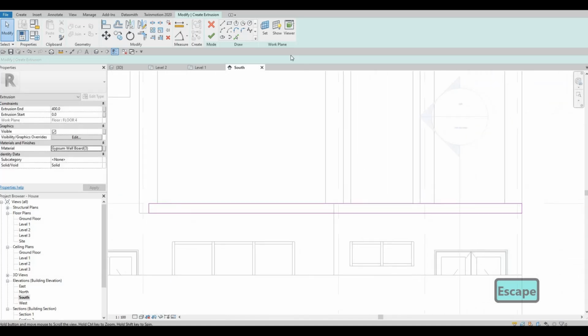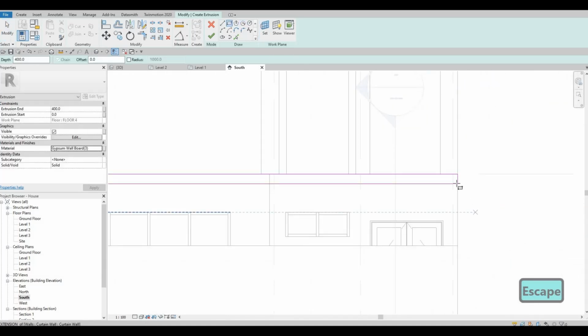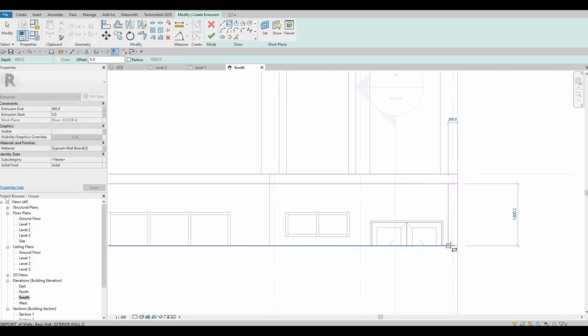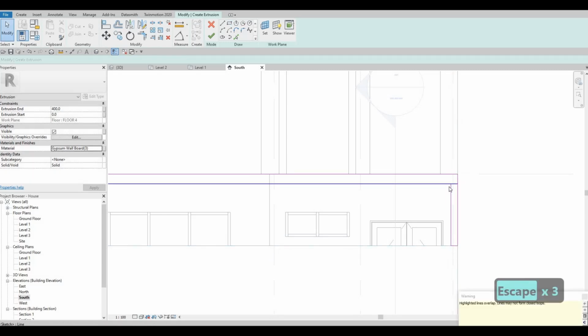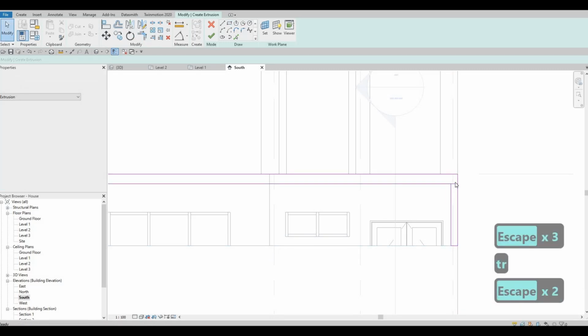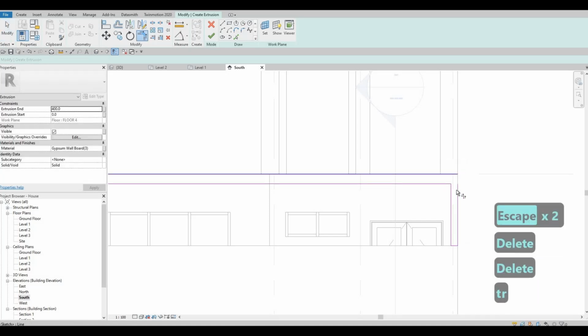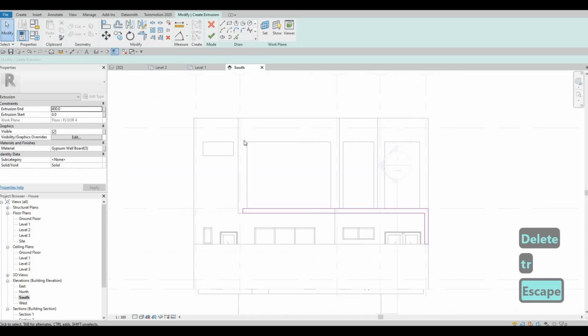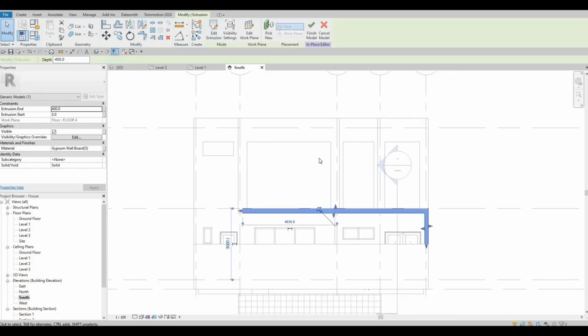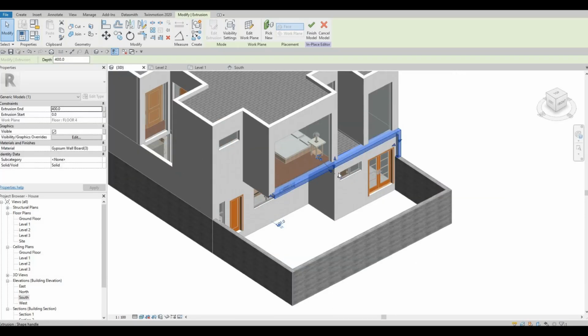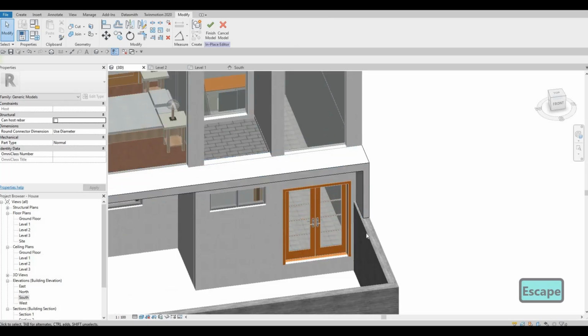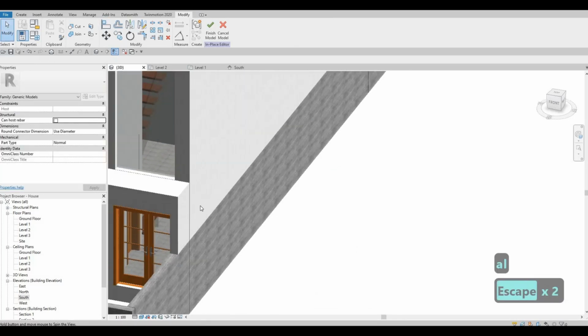We could align it there if we want to, and also what we could do is we could just add it for the wall right here. So we could trim this properly and delete all those small lines and trim it like so, and then click on finish, and I want to see how it looks. And we could extrude it as like I said earlier, and we could align it so that everything is aligned properly with the thickness and all.